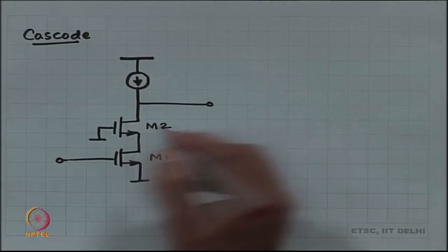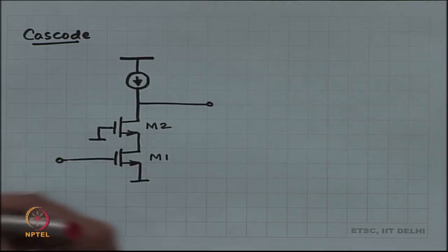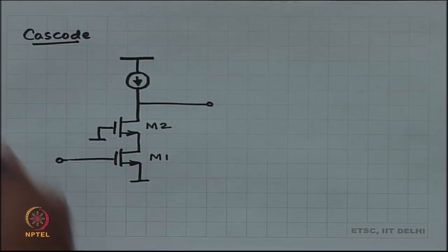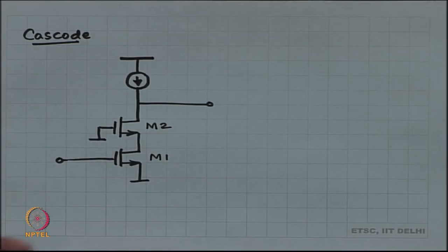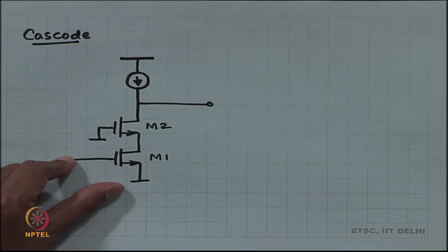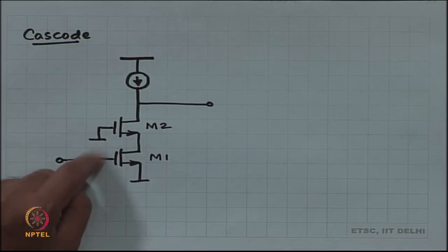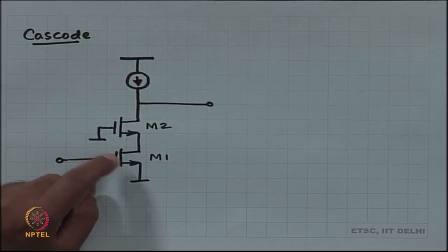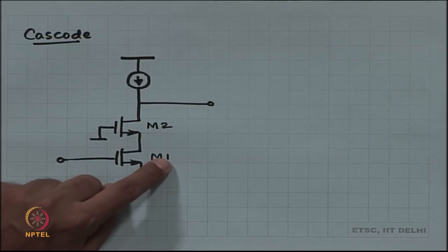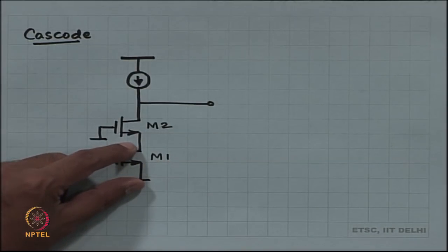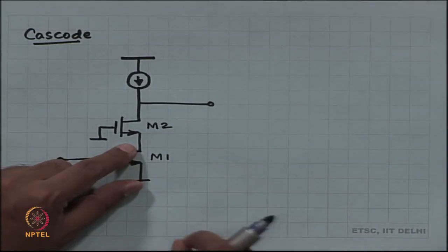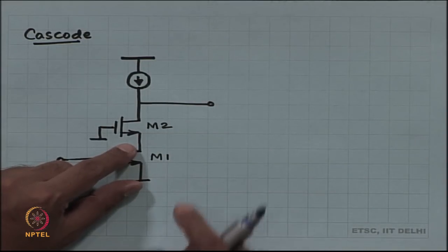If I look at the output impedance at DC, it is straightforward. It is an application of our formula. First of all, you have to apply 0 volts at the input. As soon as you have applied 0 volts at the input, this MOSFET now contains no GM, GMB was gone anyway, only RDS. So, this MOSFET M1 has only RDS1 on it, and now you apply the formula. The formula is very straightforward.